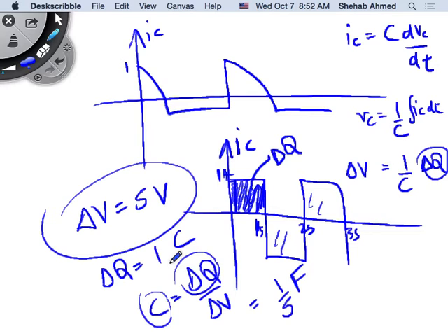But with the capacitor, I'm just showing you that if I do this, is there any difference between this and this? Nothing. At the end of the day, this is a capacitor current, this is a capacitor current. Can you calculate now the corresponding delta V if I give you a capacitance of 1 microfarad for this current waveform? Assuming you know its waveform and you can write the equations and calculate the areas, you can, right? Very simple. And it's a very nice tool because now you get an intuition.